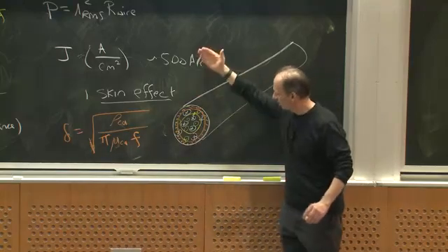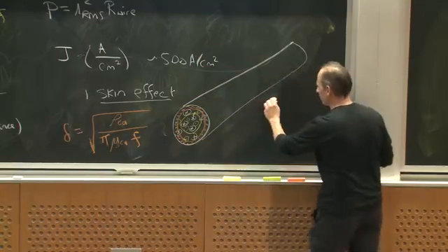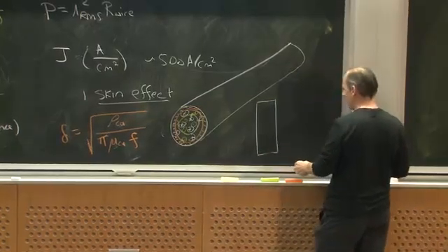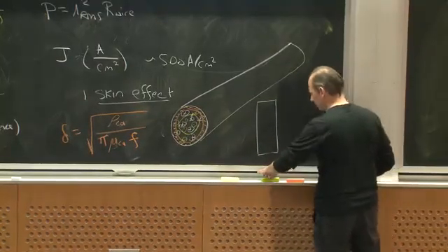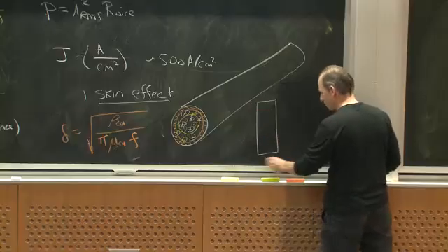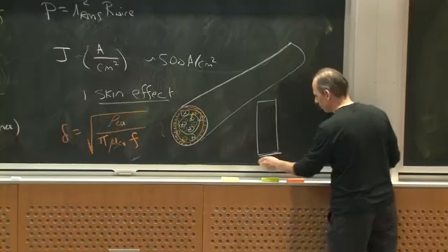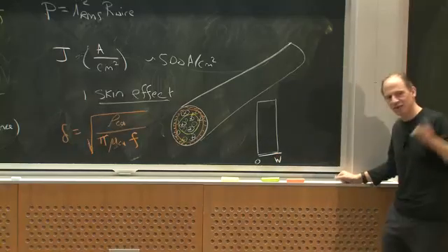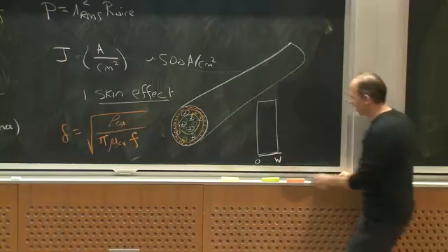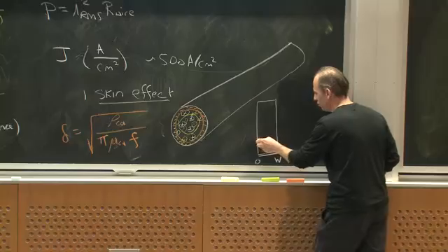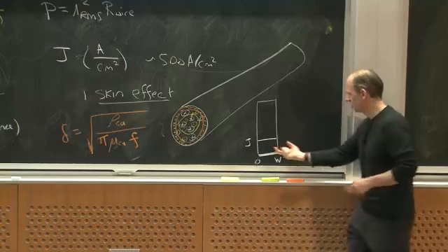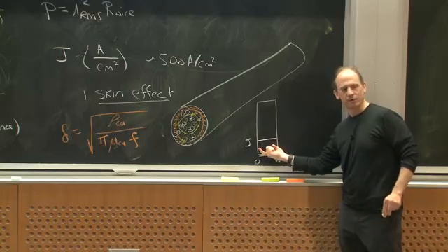Here I'm giving you a circular cross section. Let's just think of a rectangular cross section, okay? And I would say, at DC, if I looked at the current density versus the wire dimension between, say, 0 and the width of the wire, and I had single-sided conduction, which I'll talk about in a minute, at DC what you'd get is sort of a uniform current density. This is sort of J versus the depth into the wire, right?